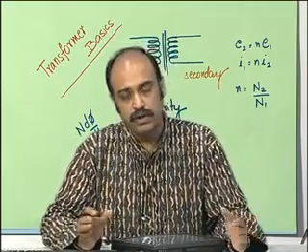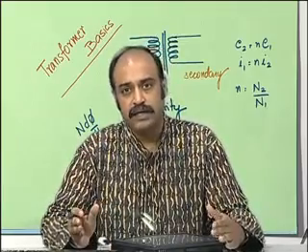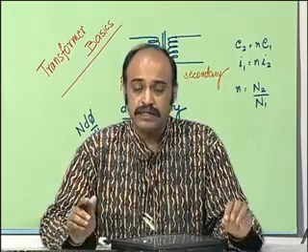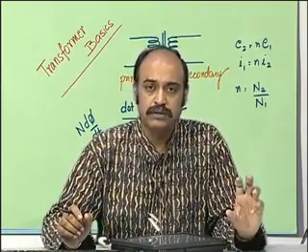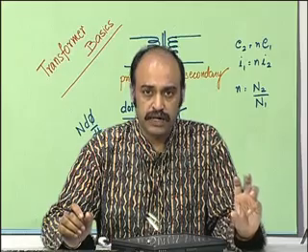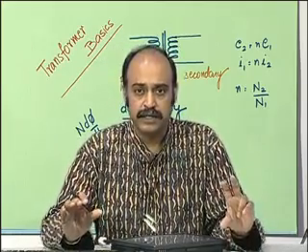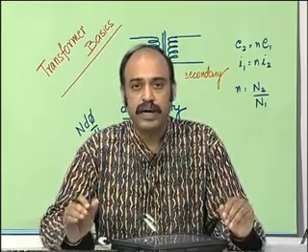Energy flows across the domain from the electric to the magnetic, and from the magnetic back again to the electric. There is absolutely no connection between one port of the transformer and the other port of the transformer. The interconnection, energy wise, is only through the magnetic domain.